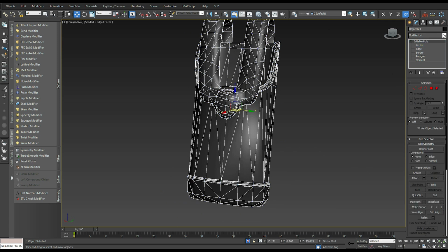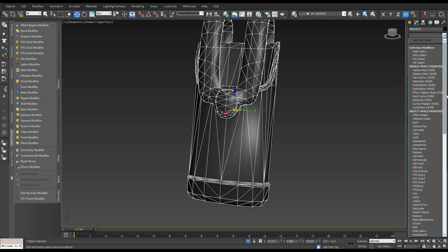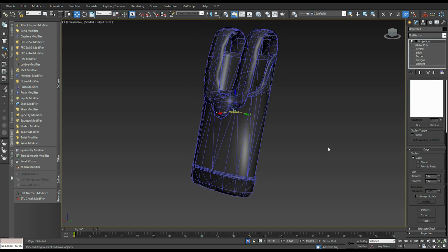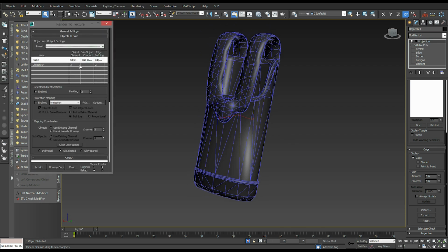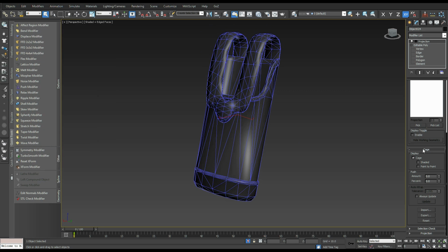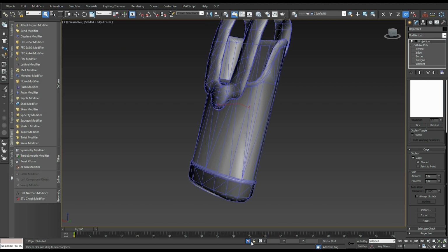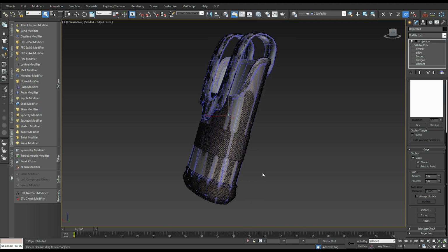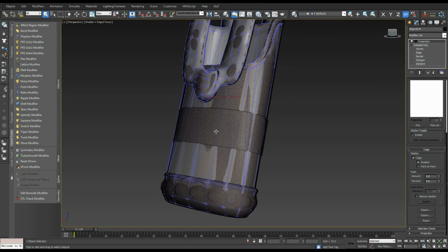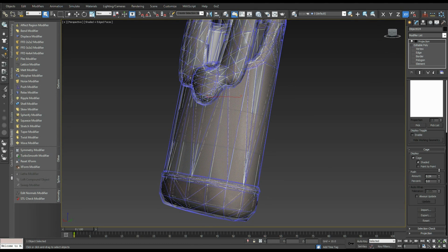The next thing you do is come over here to your drop-down list and go under projection. Where is that? Right there. This projection cage is absolutely identical to the one we were using before, when we hit 0 on our keyboard and were doing all this kind of stuff. We'll go over here, and I like to use the shaded view so we can see what we're doing. Actually, I'm going to unisolate that. From here, like we did before, we're going to push the cage out past our high poly.